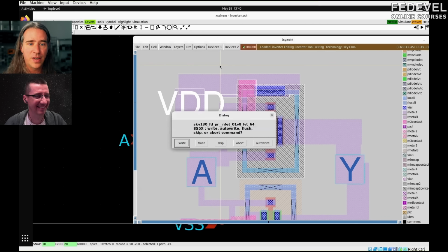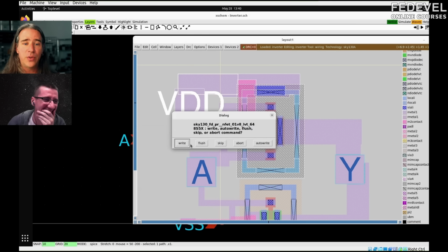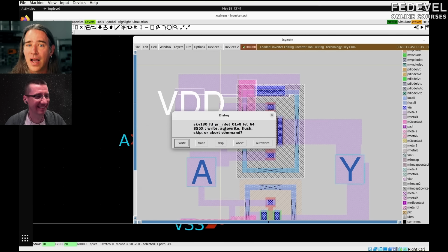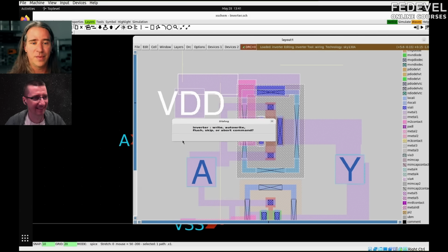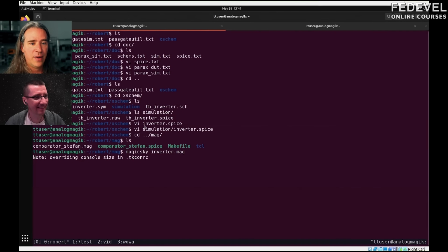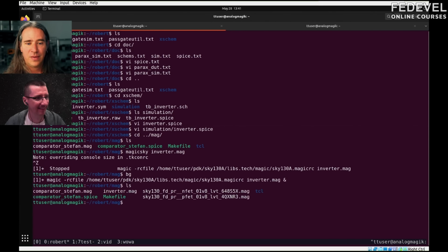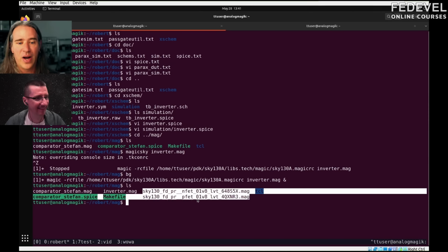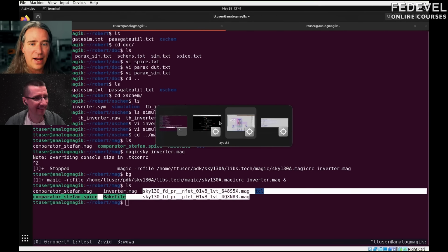And boy, I didn't save a single time during all that. So I'll do it manual style. So now it wants to write, see, it has this Sky 130. That's not the name of our file. But when it imported those things, it customized them. So it creates these Sky blah, blah, blahs and FETs. And the blah, blah, blahs are all your particular settings. So I'm just going to write that. There are two. Oh, there's a pfet and an nfet, and this is my file that I'm saving. So normally you just say auto write and it spits them all out. If we look at the directory here, we basically now have this sky stuff in here. And I still don't know how to move that to a separate directory. It gets really noisy. Anyways, so we have our magic, we have our layout.